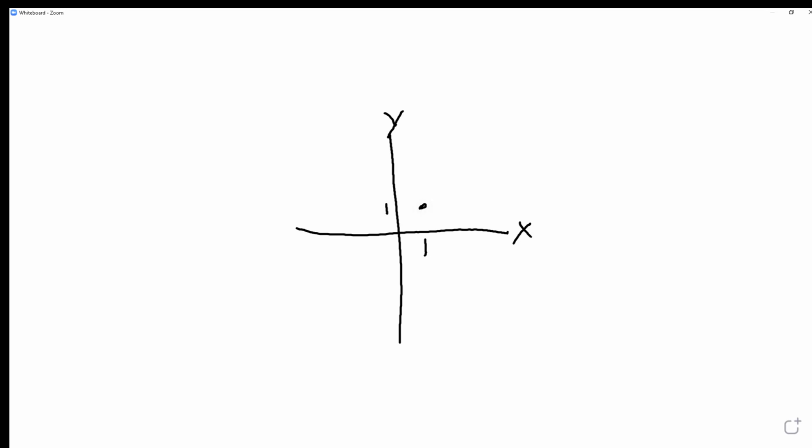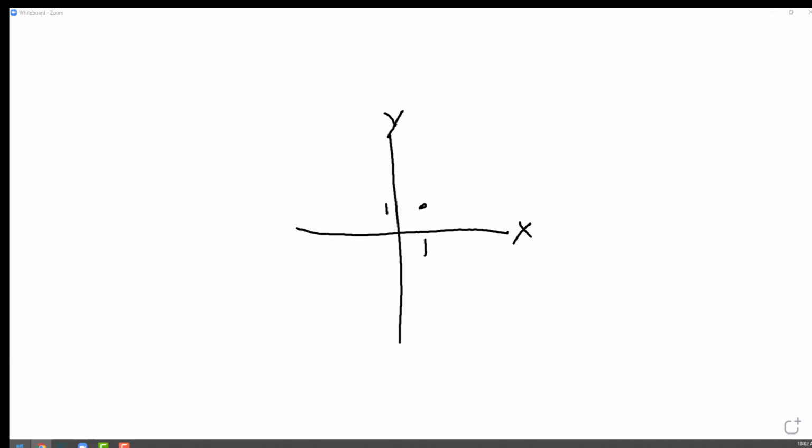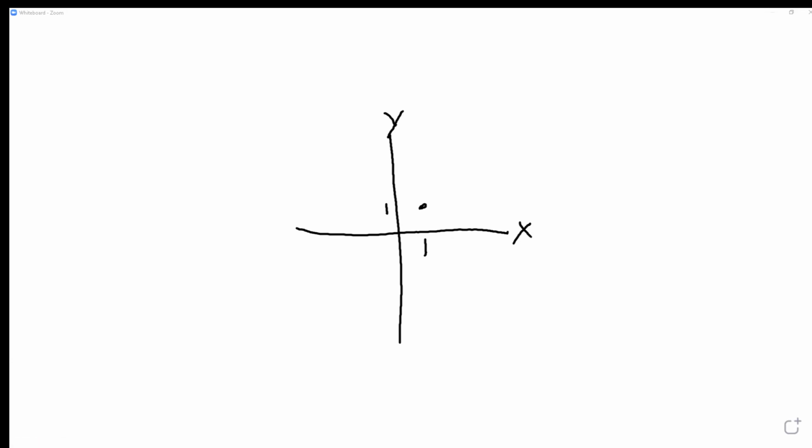Now, there are 2 main ways to program when it comes to these numbers. And I'll get you a reference here. On page 6, we start getting into absolute versus incremental positioning. Before we even get into machine codes, we need to understand that there are 2 different ways to program. I typically work with absolute, which means you have a common 0. All numbers come from 0.